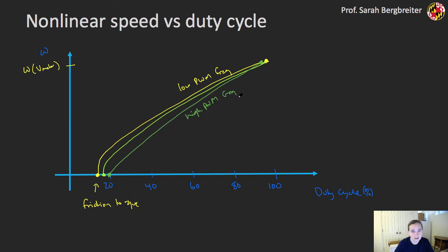And once again, the actual magnitude of that frequency is going to depend on the actual mechanical situation that I'm in, so the kind of inertia and torque that I'm trying to provide with my motor, as well as the motor design itself, so the inductance and resistance in that motor, effectively the time constants that I have to deal with in my system.